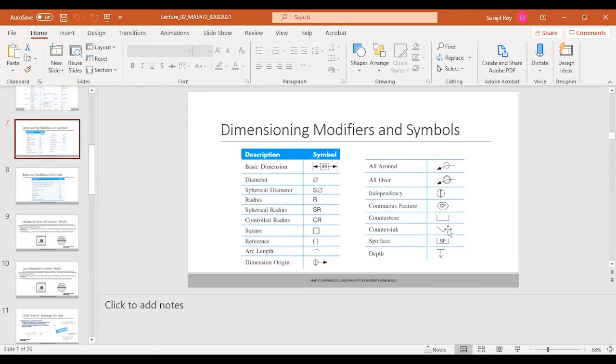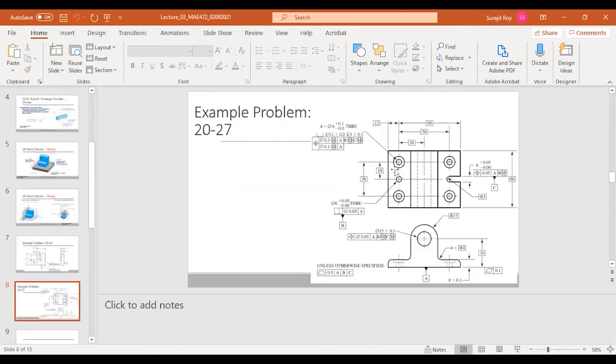So these are basically two different types of machining operations. So if you have a flat face, that's counter bore, and if it has an angular face, basically it's a blind hole you are making, then you basically have a counter sink. And if it has got a flat face, it's counter bore. That's the difference. Okay. Thank you. You're welcome. That's not counter sink, it's counter bore actually. And these are basically saying it has got a diameter 12 millimeters and a depth of 3 millimeters. That's it.